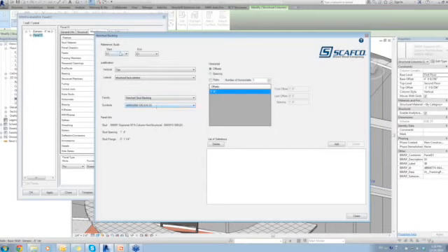But first I want to specify the studs I need to attach my notched backing to. I said I want to go from member S5 all the way to S8. I'm interested in the center justification of this member. I want to attach it to the interior face of that panel. I have the option to select the notch stud or notch track.